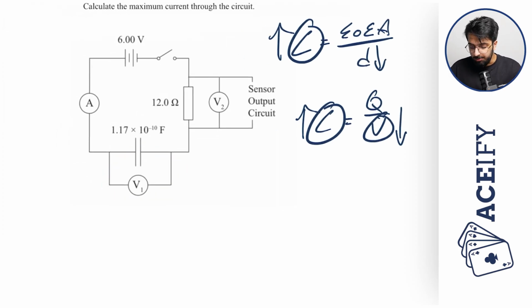And so now, the voltage across the capacitor is no longer equal to the voltage of our power supply. And so that means charge will begin to flow onto the capacitor, and so now there is a current present in the circuit. Remember before, when the capacitor is fully charged, there is no current flowing in the circuit because there are two equal opposing EMFs, and so no current will flow. However, now that the voltage across the capacitor has decreased, it is no longer equal to the voltage of the power supply, and so now charge will begin to flow into the capacitor, and so there will be a current present. And so this means that the ammeter will detect a flow of current.